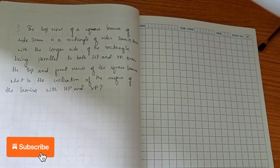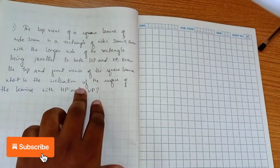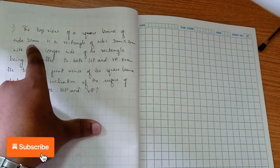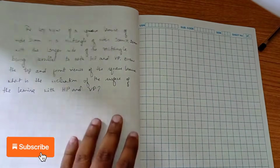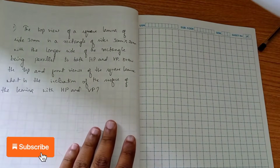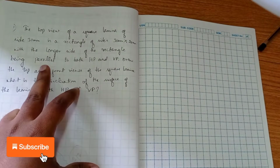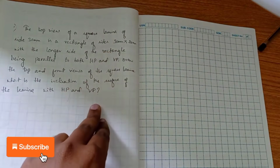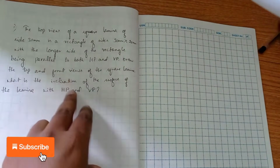Today we are going to learn another type of problems on rectangles. You see in this problem, the top view of a square lamina of side 30 mm is a rectangle of side 30 into 20 mm. So it's like your isosceles triangular problem, wherein first we have to construct a square of dimension 30, and your second diagram will be a rectangle. After that we have to proceed with the longer side of the rectangle being parallel to both HP and VP.